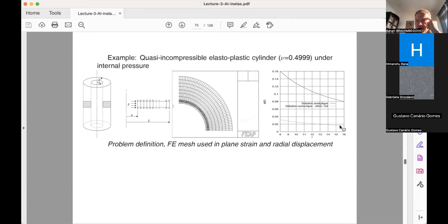Now, these are your isoparametric elements. They have an order of magnitude smaller displacement because, again, they lock because both elastic and plastic incompressibility are here. So really, locking is very severe. And if you have incompatible modes, basically you can be right on the curve.